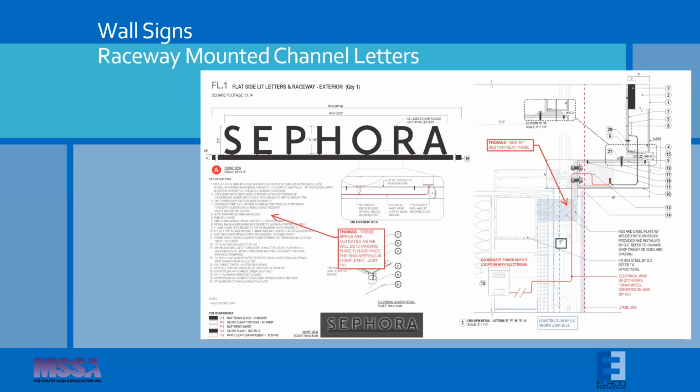If these letters are mounting on top of a canopy, it's crucial to the mounting design to obtain a thorough survey of that canopy frame, including, if possible, any structural drawings that may be available from your client.